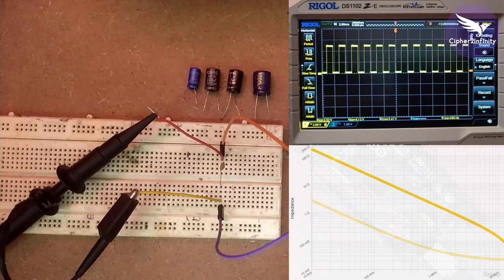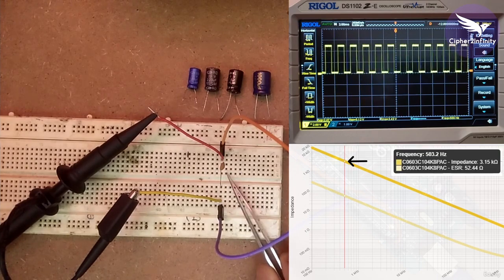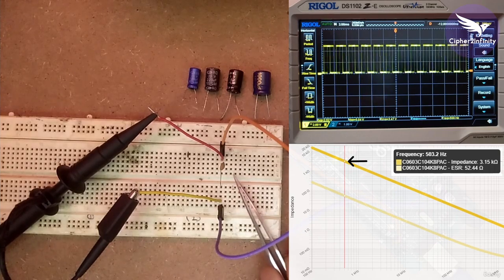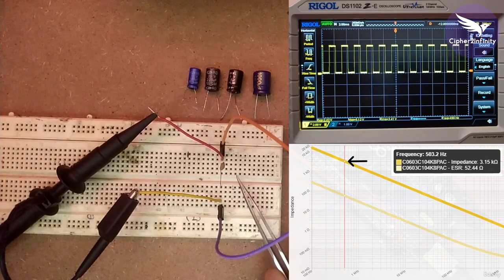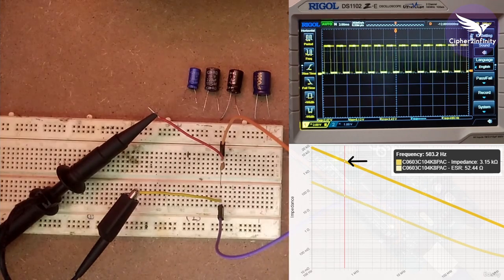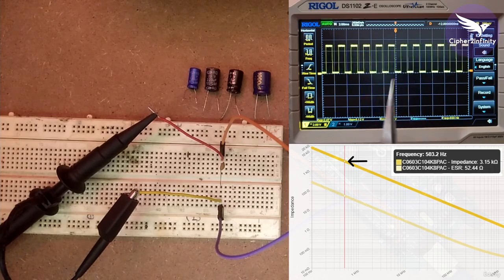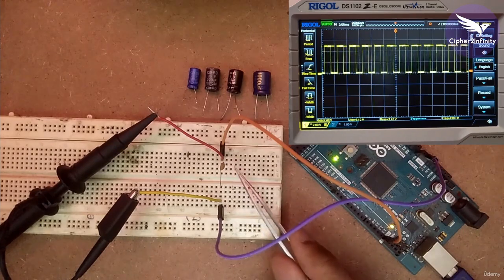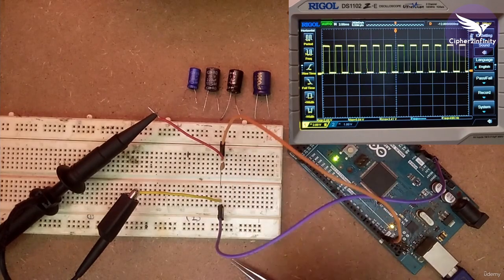Even higher impedance. I will put the image of the impedance versus frequency plot for this particular capacitor, and you will see in that plot what impedance this capacitor is providing at 500 Hz. Right now I think it's providing an impedance of around 1 or 1.5 kilo ohms. That's the reason we are still getting that frequency on the output side, which you can see on the DSO. So this tells us that this capacitor is not good at all at filtering this 500 hertz frequency. So I will remove this capacitor now.